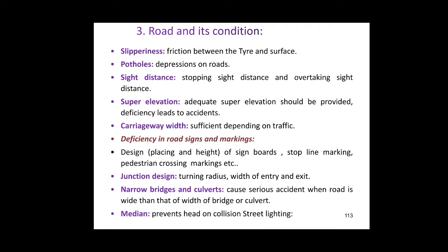Next, deficiency in the road signs and markings. The design, placing and height of the signboards, the stop line markings, the pedestrian crossing markings, etc. If they are not provided at the design heights and placings, they will lead to the negligence of the road user, thus causing accidents.